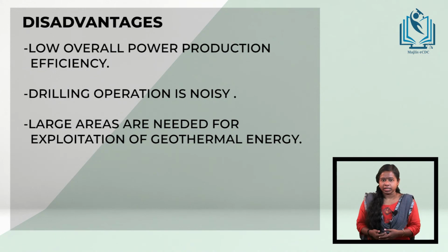Next are the disadvantages. The first disadvantage is low overall power production efficiency, about 15% as compared to 35 to 40% for fossil fuel plants. Next, drilling operation is very noisy. The third disadvantage is that large areas are needed for exploitation of geothermal energy. And the fourth one is that withdrawal of a large amount of steam or water from a hydrothermal reservoir may result in surface subsidence or settlement.